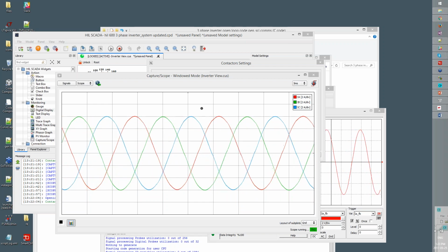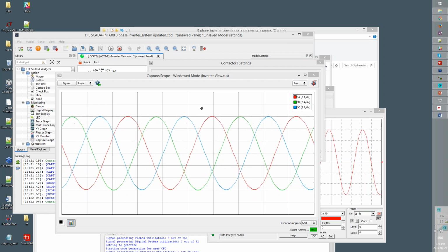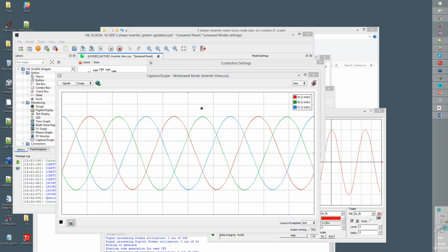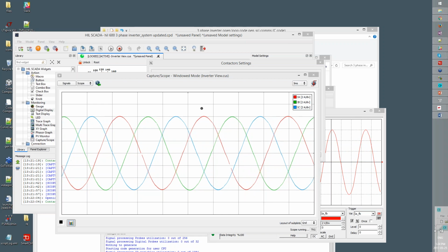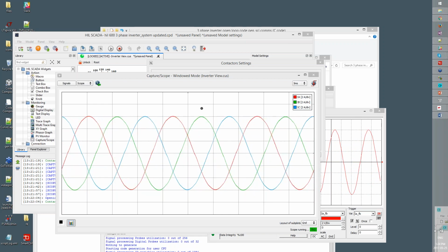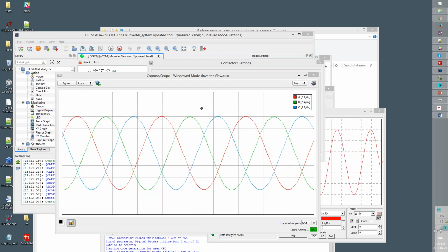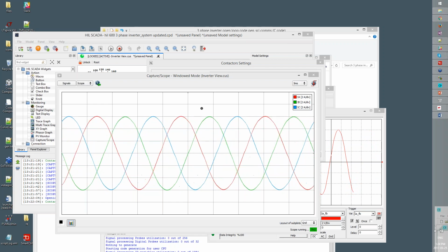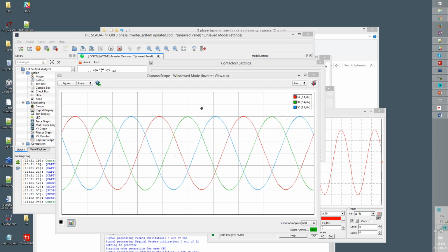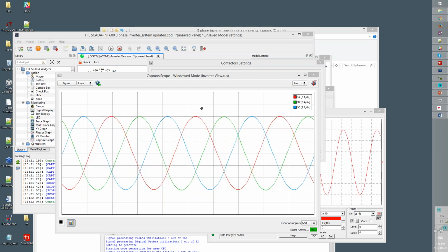We have a follow-up part that went into production last year, the F2837x series, and the superset part is the F28379D, which has dual instantiations of the CPU core along with new accelerators, our parallel coprocessor called the CLA, double the memory, new peripherals, etc. I'm sure that part is also supported by Typhoon, and it's the part that new applications are moving towards to get the latest and greatest of everything from C2000.